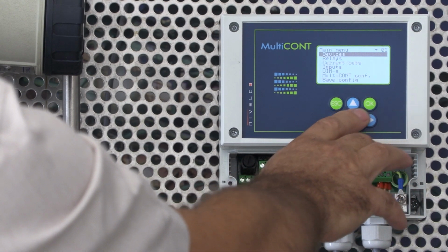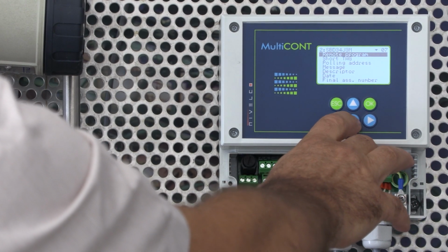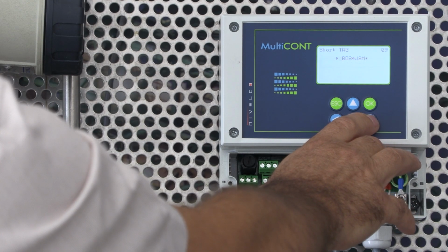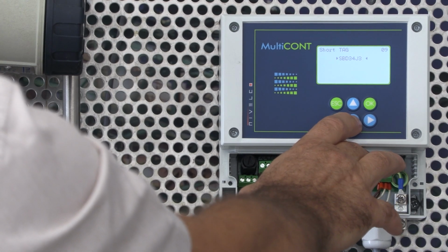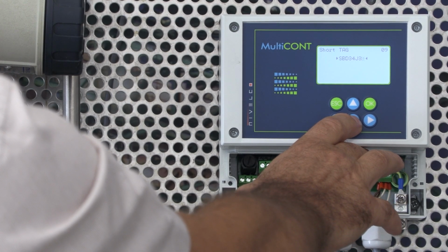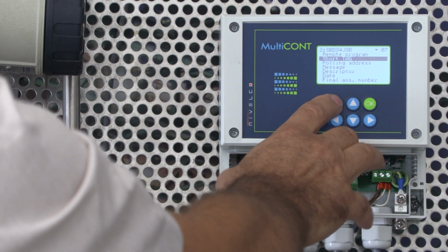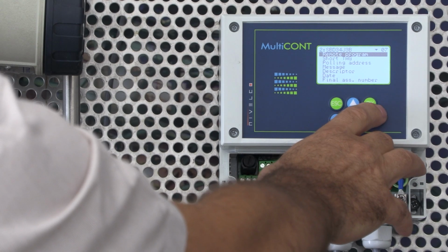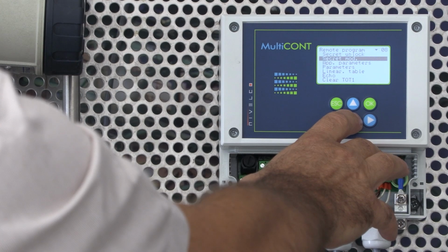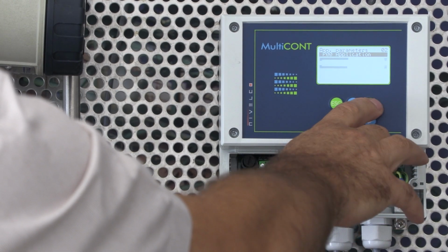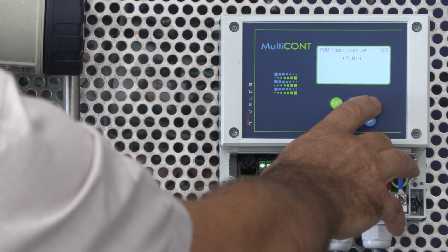To rename the new device, select it in the Devices option of the main menu. Then go to Short Tag, enter a name. And press OK to save. To set the unit system of the new device from metric to US, go to Remote Programming, select Application Parameters, select P00, enter 0101, and press OK to save.